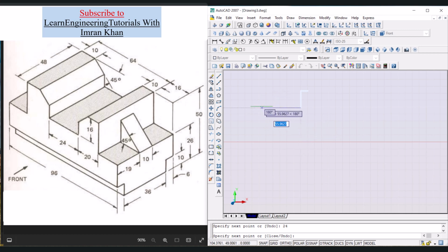Now in this direction we have to calculate, or it is also given over here, this is 16 length and 16 will be on the other side as well. So in this direction give the value of 16, enter. Now regarding this height, this is also 16 because 26 minus 10 is 16. So bring the cursor in this direction. When the tracking line is in front of you, write the value of 16, enter.